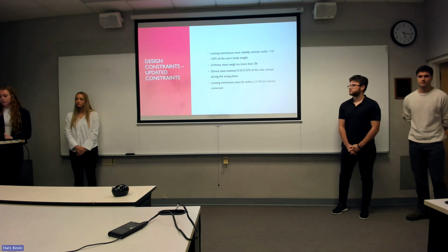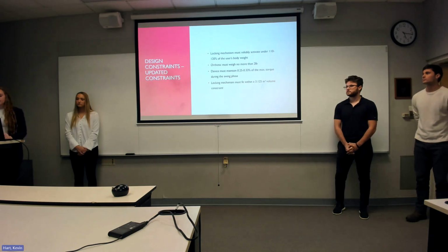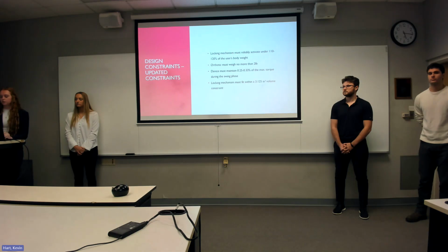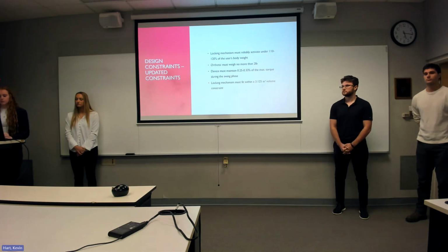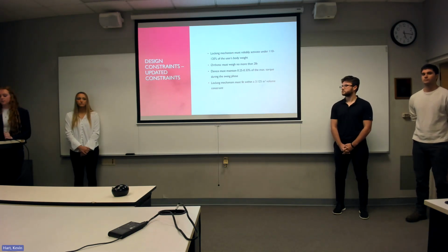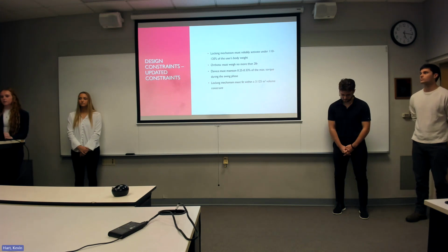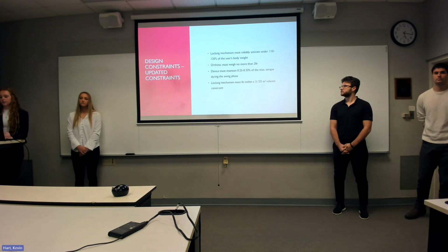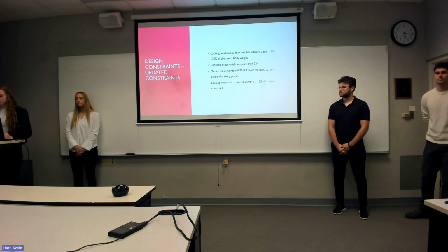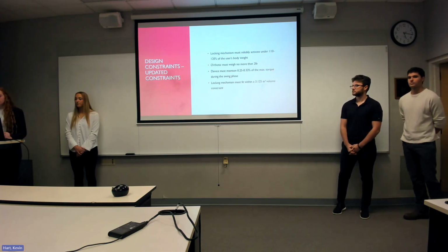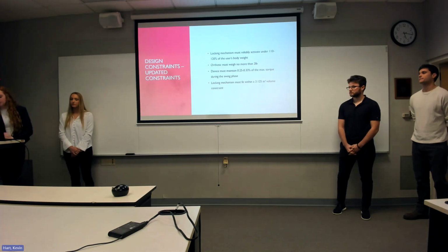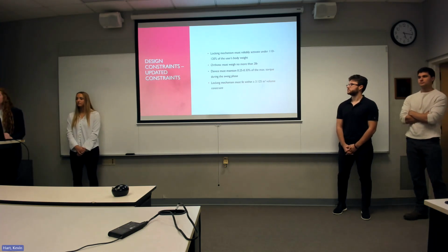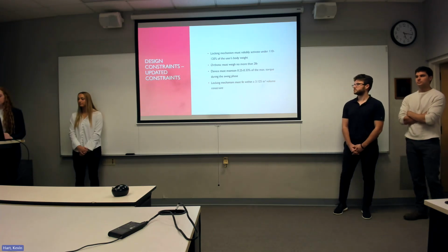We replaced the general weight limit with a system level constraint requiring total orthotic weight to be no more than 2 pounds. This ensures that the mass is controlled where it matters most, which is around the ankle. Rather than simply stating that the ankle must be maintained, we now define performance in terms of torque during the gait cycle and the swing phase, ensuring the device provides enough resistance to prevent that toe drag. Finally, we decided to add a strict volume constraint to ensure that the locking mechanism fits within its physical space as well as the user's shoe.